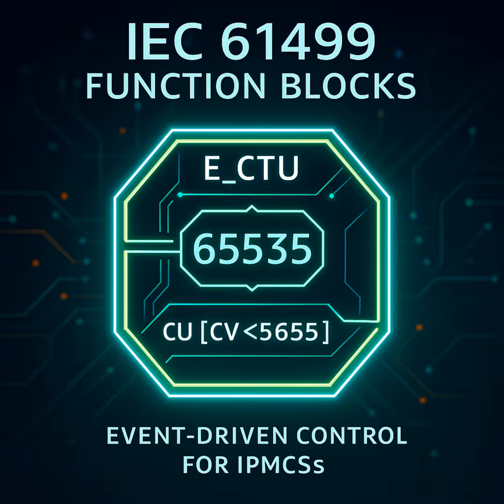This is vital when your control logic is spread out. Maybe some function blocks are on the main controller, others are out on remote I/O modules connected via Fieldbus. You can't rely on a single synchronized scan cycle across all those devices. Think about something like counting hydraulic cylinder strokes for precise batching. That counting logic might be running right there on an intelligent valve controller out on the machine arm. Right, what the standard calls a mapped resource.